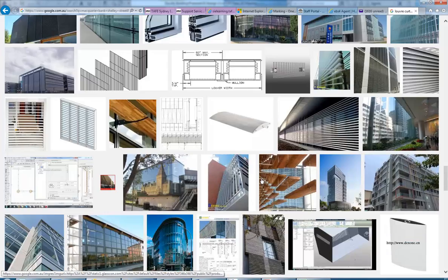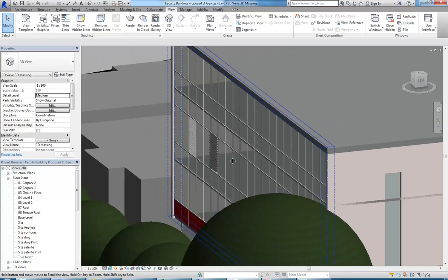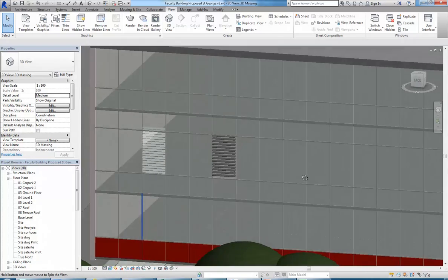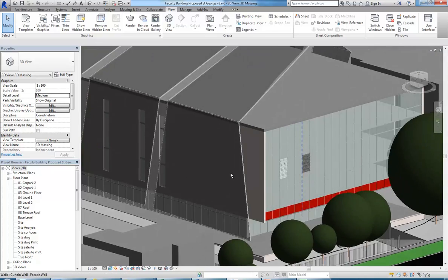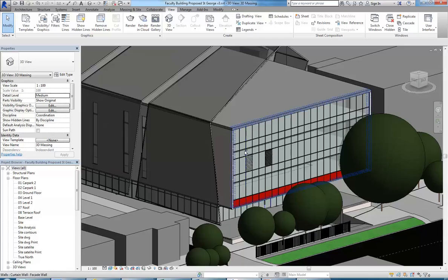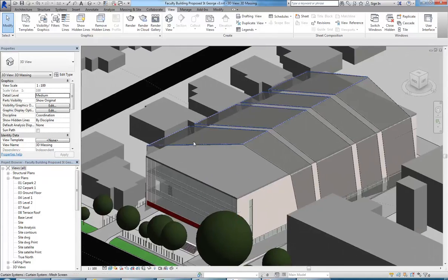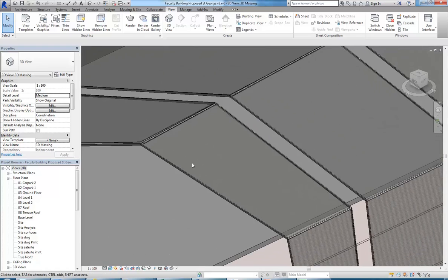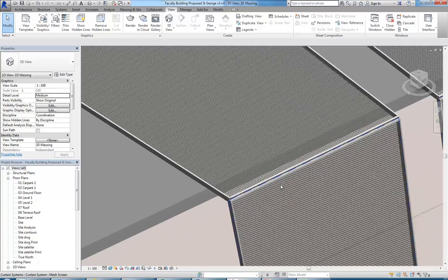So anyhow, just maybe think about what you can do with the pattern of your openings and make the facades more interesting by varying those. You can do similar things with windows, of course, and then look at using curtain systems for sun shading. So here you can see I've turned that massing that I've done earlier into a curtain system there.